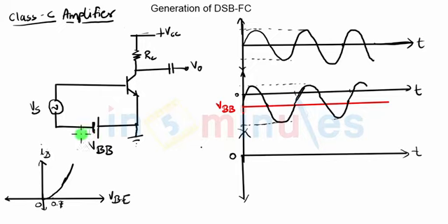So when I give negative voltage to the base, which is of P type, which is the anode of the PN junction, because this is NPN transistor, emitter will be the cathode of the PN junction. You can simply look at this base emitter as nothing but a PN junction. So because anode is at negative potential compared to cathode, I say that we are biasing the transistor below cutoff.